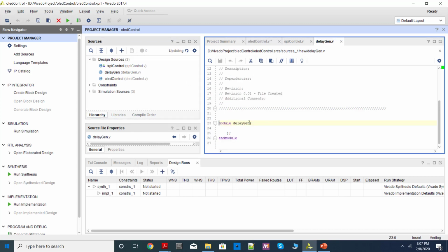And this is how we do. We'll use a counter, and remember this guy is also going to run at 100 megahertz. We need to find the counter value so that when that counter value reaches, we have the delay. Okay, that's the basic logic we are going to use. So it gets a clock, and whenever you need a delay, you will make this particular signal, delay enable, high. So you're basically telling the delay generator to enable the delay generation. I want to get the delay, and if you're done, you'll have an output signal, delay done, which will basically say it has generated that much delay.